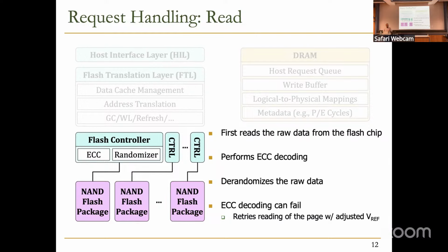There might be pages that you write in your SSD and don't touch for a long time. When you want to access them, people have shown that they are much slower. So the read throughput you're getting from the SSD is much lower when you want to access all data, essentially. The main reason is that you need to retry the read until you get it correctly.